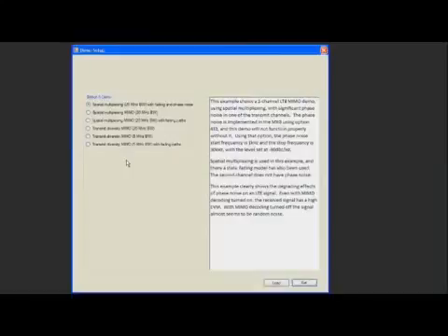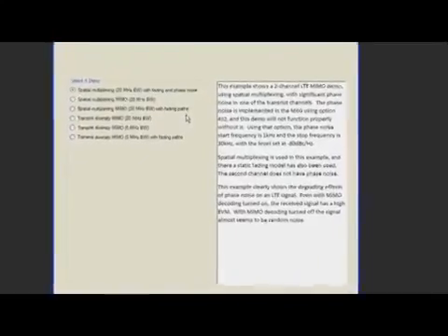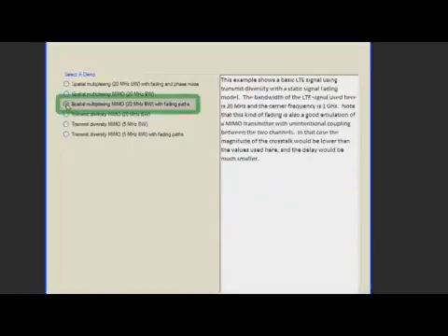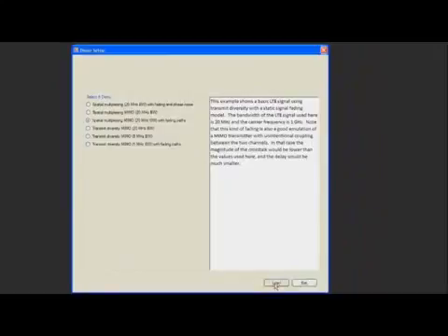The next example will demonstrate analysis of a 2x2 LTE MIMO signal with impairments due to static fading. To set up this demonstration, follow the same steps as before, but select the option with fading paths in the custom demo software instead of the unimpaired demo.